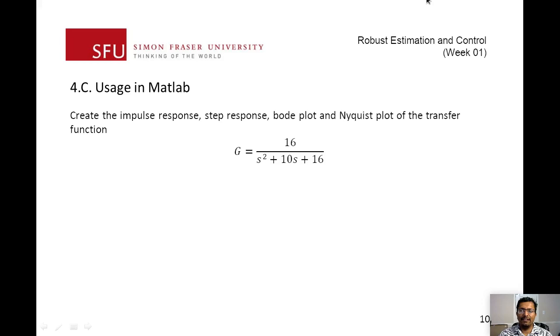All right. So next, we're going to look at basic usage in MATLAB. We're going to create an impulse response, a step response, Bode plot, and Nyquist plot of the transfer function 16 divided by s squared plus 10s plus 16. Again, if you're doing it manually, it's a lot more work. We're going to use the power of MATLAB here.